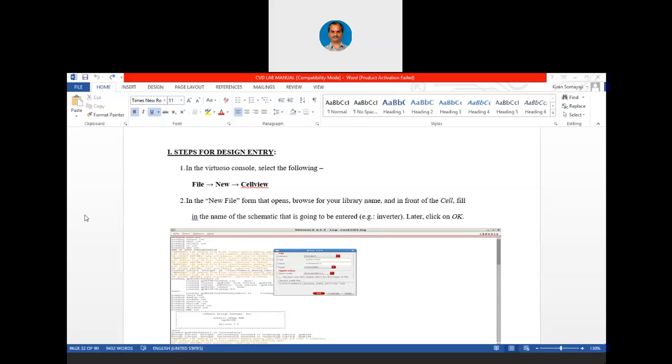Now, this group of transistors is not just transistors. The layout of transistors is also made and it is available in layout form in the library. That means when you pick up a PMOSFET, the PMOSFET's layout is already made by the Cadence people, along with the source, drain, gate, polysilicon, oxide, substrate, and metal, everything.